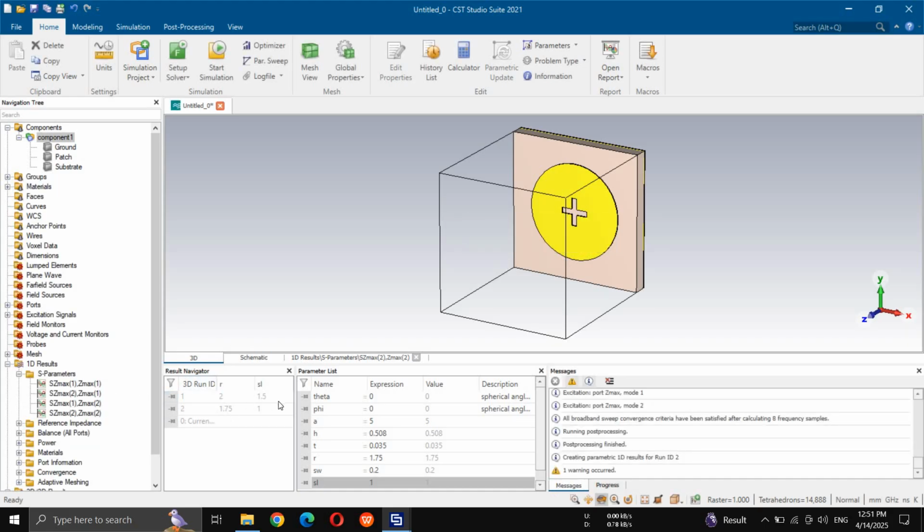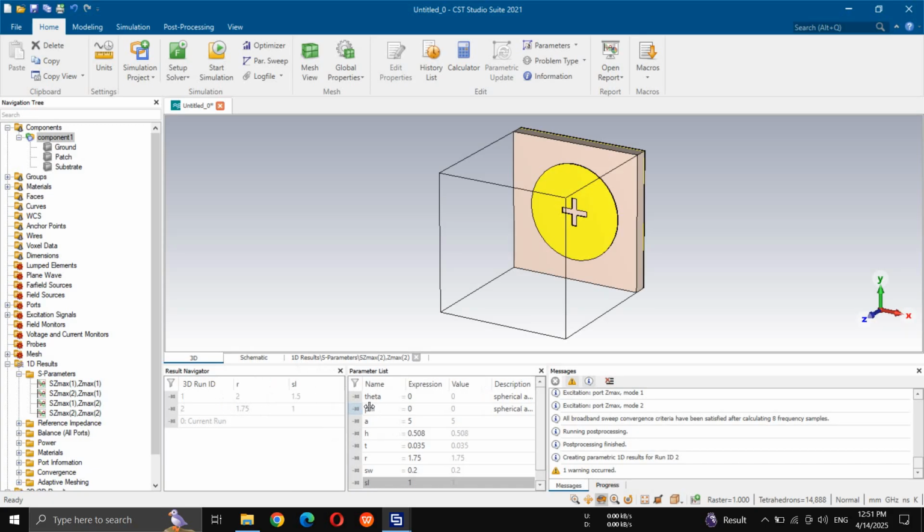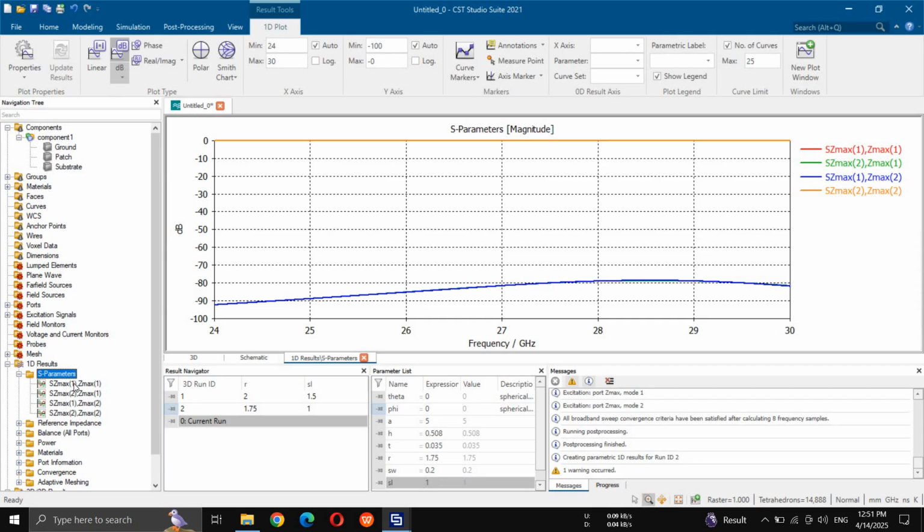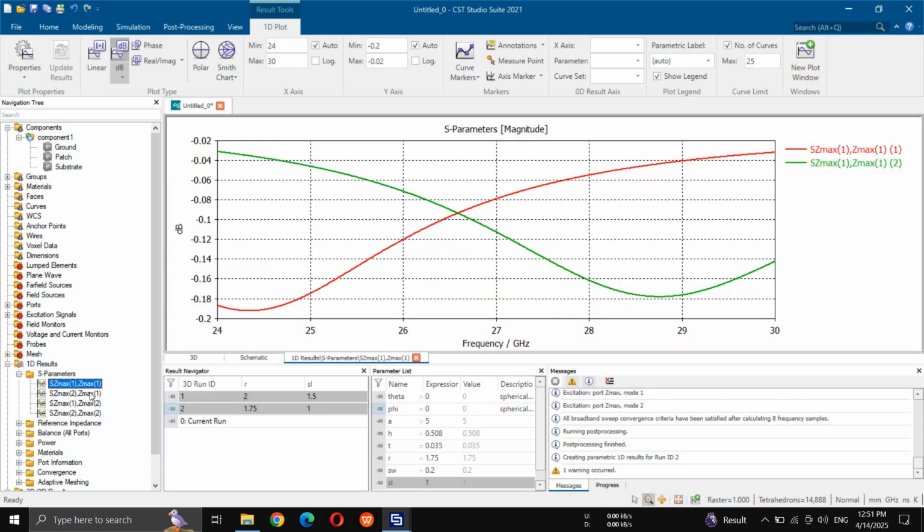So let's see. Yeah, we have these. Okay, you can see here we have two different sweeps, and let me check the results. Okay, just this one is enough. The first sweep is giving us this amplitude. Both the amplitudes are more than -3 dB, so it is a good reflection. If it were lower than -3, like -4, -5, it would mean that it is very lossy and not reflective. But we use a reflective unit cell with complete ground, so obviously that also helps.